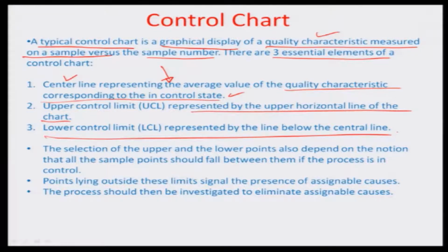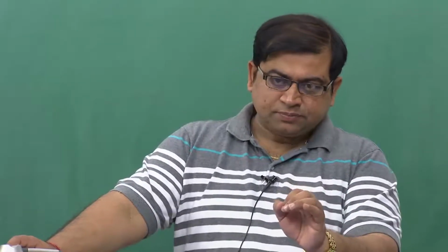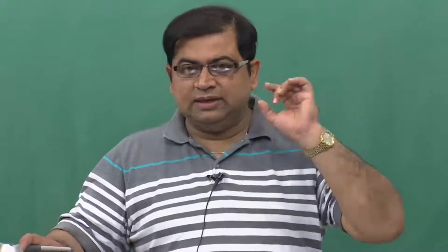The idea, which you have to understand clearly, is related to process variation or process capability. You have a center line, an upper specification limit and a lower specification limit related to the production being done in the process. When you need to estimate the capability of the process toward a certain design, you have to illustrate the specification on the design and see whether those specifications are lying within the process or vice versa.